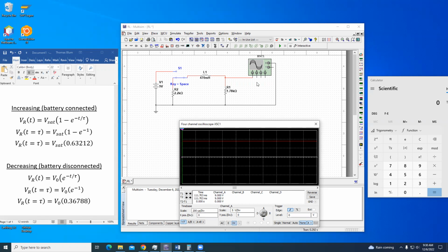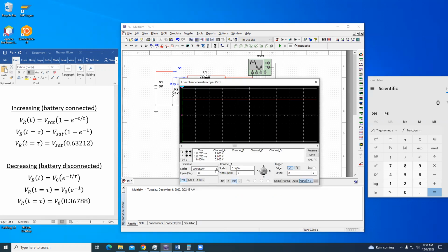So now we can play with this time scale. I want to find this up and down more rapidly. I can reduce the time scale. And then when I find, oh, here's where it's rising, then I'll lower the time scale to stretch it out. Stretched out a little bit more. But sometimes if you're too stretched out, it's hard to find where the rise and the fall occur. So you'll want to play with this time scale.